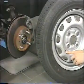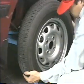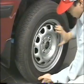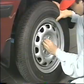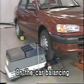When wheel balance is attained, fit the tire back on the vehicle in accordance with the register mark you made earlier. Check again that the tire does not have runout. Then check the on-car balance.